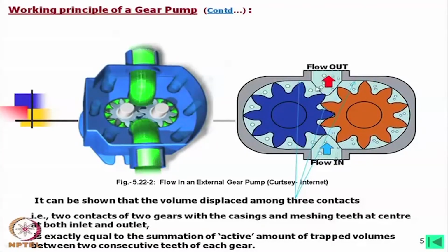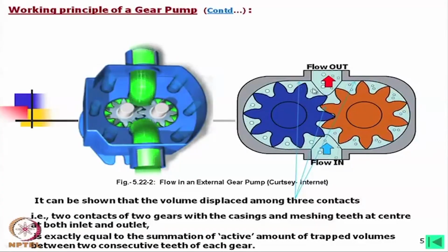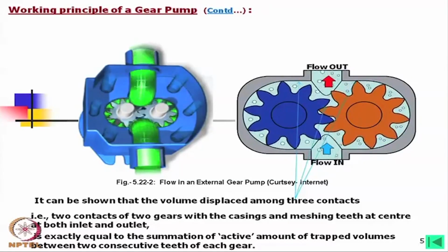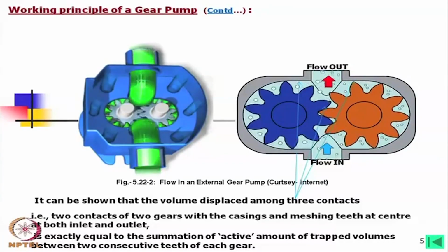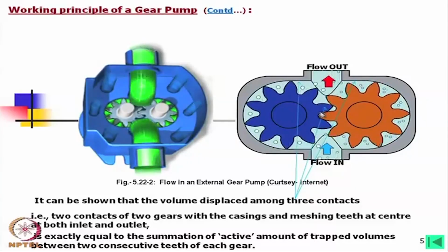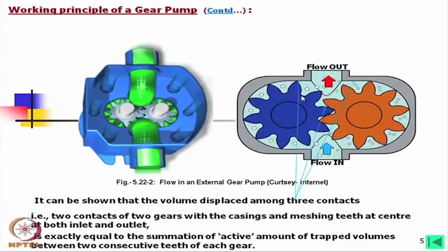However, if we calculate the total displacement of this area during the suction and compression, then automatically that will be deducted from the calculated area. We need not bother about how much pocket. That means, if we give more undercut to these gears, that will not matter, nor the root fillet. If we increase the root fillet, that will not really matter.